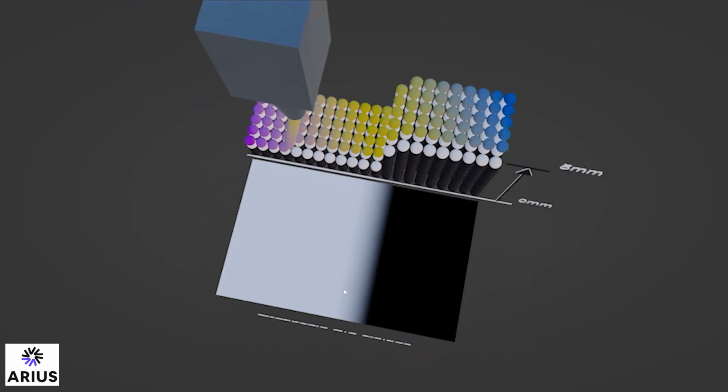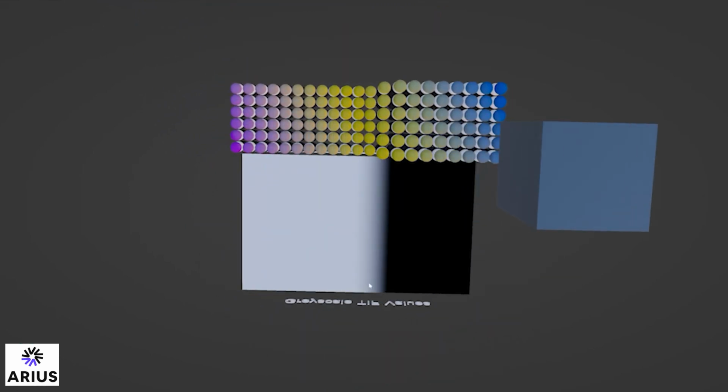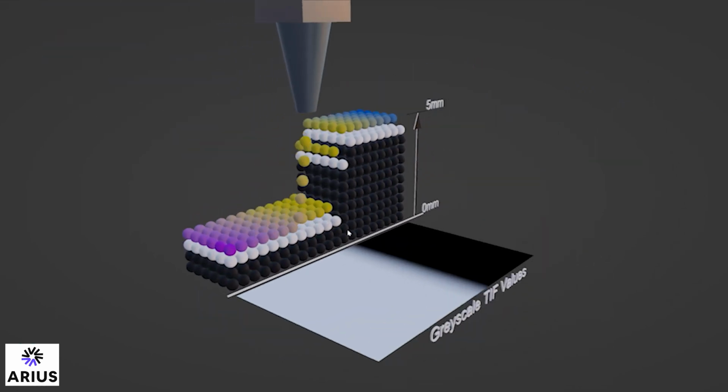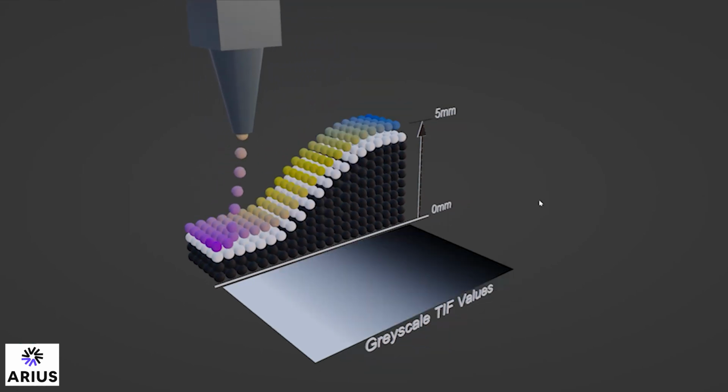But from a top-down view, the printer is doing a brilliant job of laying down the color in a linear direction from a two-dimensional perspective. But we're dealing with a 3D surface, so it's not going to hit this vertical wall here. That's the issue we're dealing with, and what we want to avoid by softening the contrast in the grayscale elevation image. Softening like this will eliminate any possibility of a wall. The gradient here is smooth over a generous number of pixels, and the result is a smooth blend and no wall.